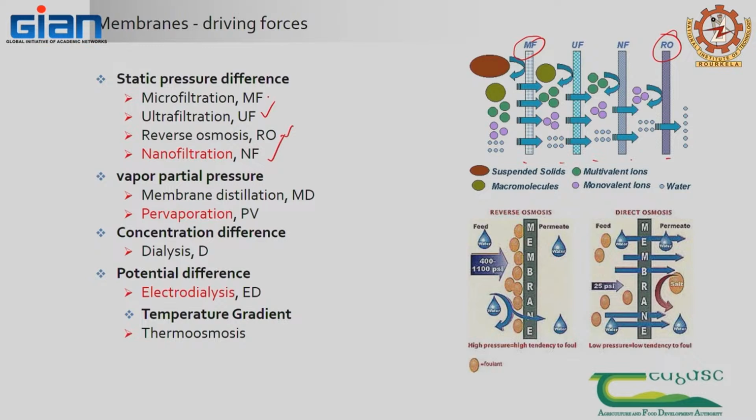We should not treat microfiltration and ultrafiltration as the same, because in ultrafiltration we are talking about molecular weight level, which means proteins, sugars and all those things are separated through ultrafiltration, based on molecular weight. It is not that you have whey and put it straight into ultrafiltration, it will clog.